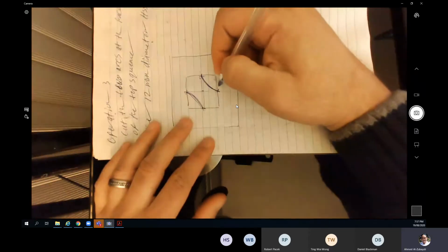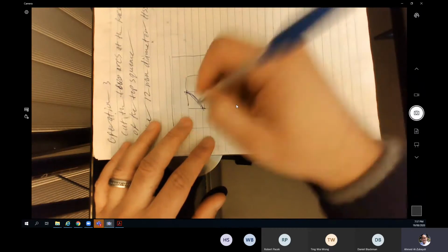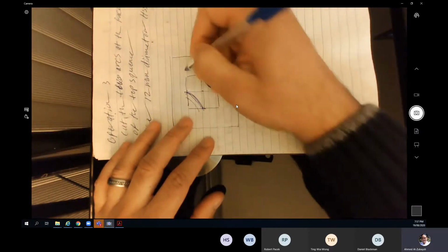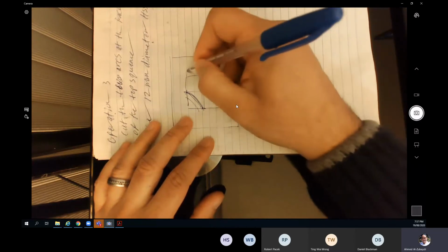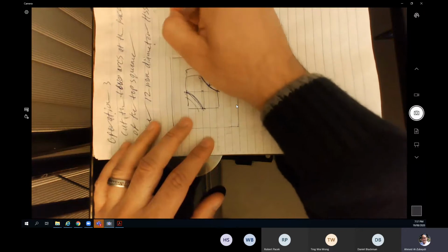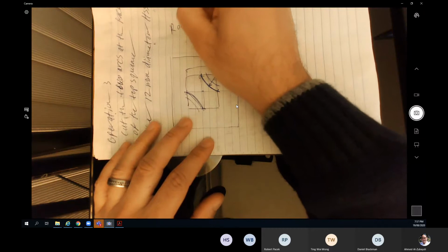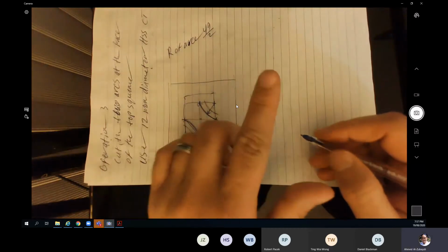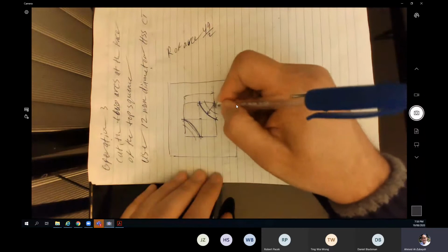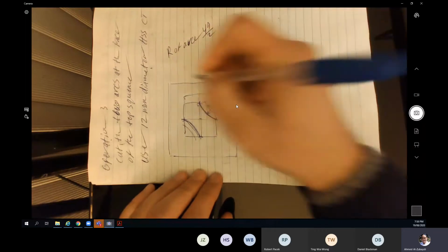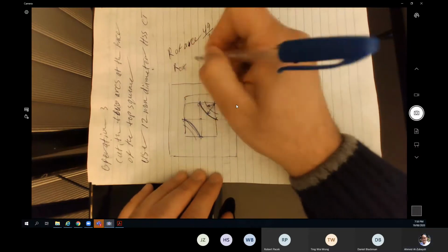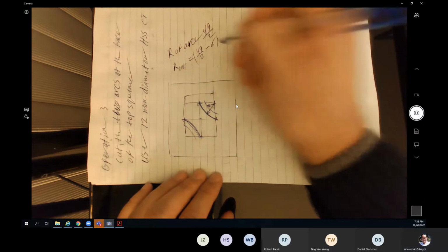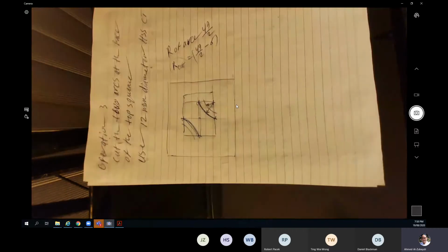The useful one for us is again to sketch another arc, which is going to be smaller by 6 millimeter. So what is the radius of the bigger arc? It's going to be half of this length. If this one is 49, the radius of the arc is 49 divided by 2, which is equal to 24.5. But the R I'm going to use for my G coding, the R of the cut, is going to be equal to 49 divided by 2 minus 6 millimeters. I'm going to use this one in the coding of the G02 or G03.